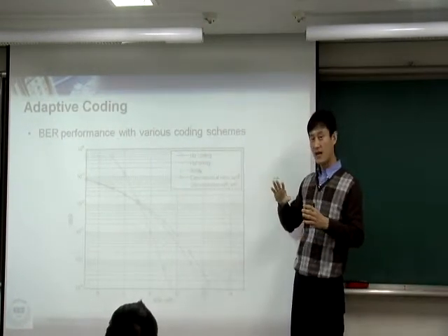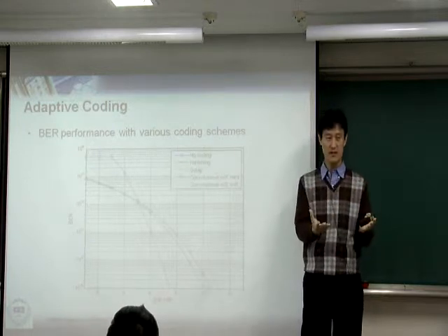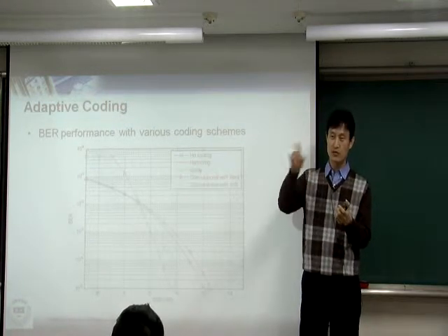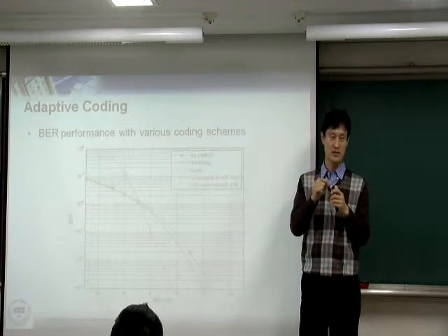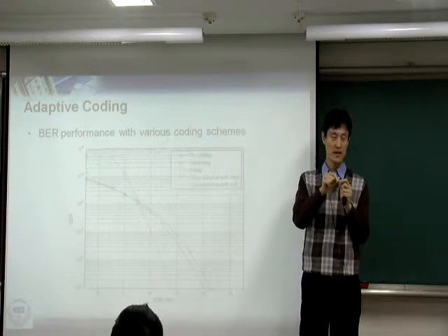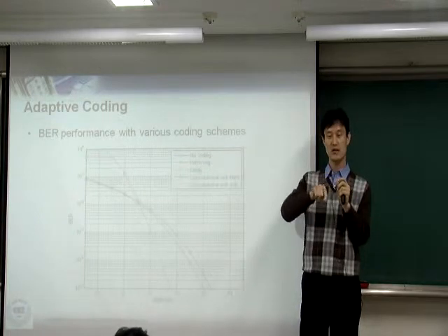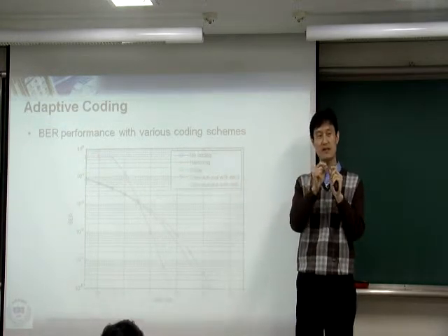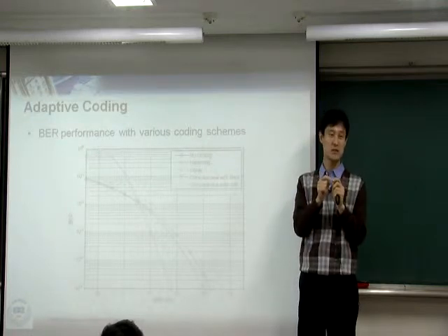But that's the hard decision. Inside the decoder, while you're doing iteration, you can make a hard decision for each bit, and then that hard decision has influence on all the following bits. So how to make a temporary decision is important.